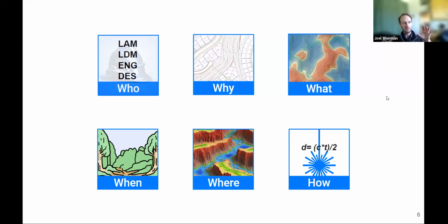And then this is an interesting component. So where LiDAR is being performed really has to do with the topographic profiles of the project area and then the amount of vegetation. So historically, deriving original grade data could have been done using traditional surveyor methods. Maybe it's using a total station or a GNSS receiver if you're able to get into the canopy and get good signal, or even just other traditional methods. And you're able to create a generalized distributed network of data points that you can assume have continuity between them, right? I don't know if you guys are familiar with a TIN model, a triangulated irregular network. Effectively, it's taking all those points and creating a surface out of all of them.